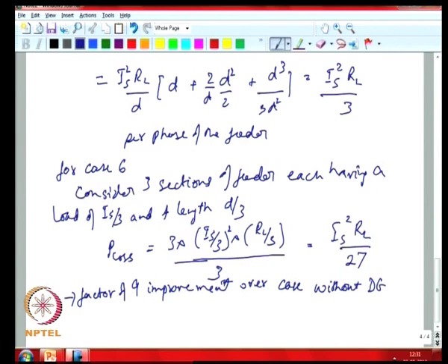So, you can see that there can be substantial improvement in terms of reduction in losses and possible improvement in voltage profile by appropriately siting DG, which you would have also heard from people who say that there can be a possibility of reduction in transmission and distribution losses by the introduction of DG into the system.